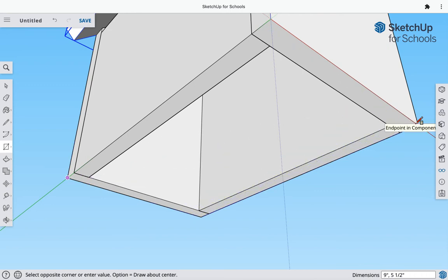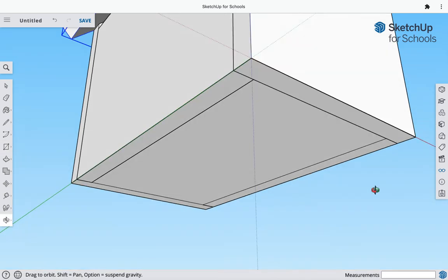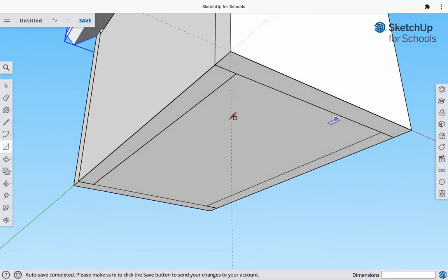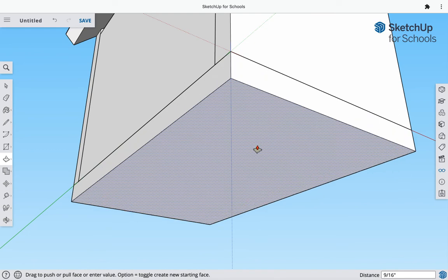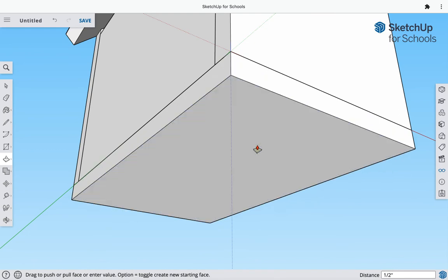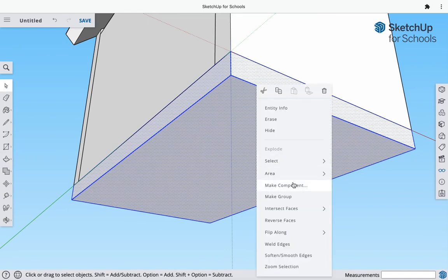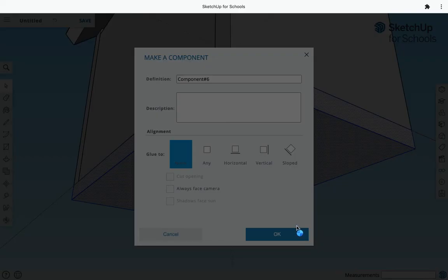So there's not really much to see because there's already edges there. But if you click, release, move your mouse and then make your second click there, it's going to actually cover up everything. Okay, so I will admit that this is a confusing look because you just made a plane, but remember that plane has no thickness yet. So don't forget to click on your push-pull tool, click on this plane, drag it down this direction, exactly 1/2 inch, because that's your material thickness, so 0.5, and then press enter. And then please don't forget, make it a component. Very important step to always make those a component.